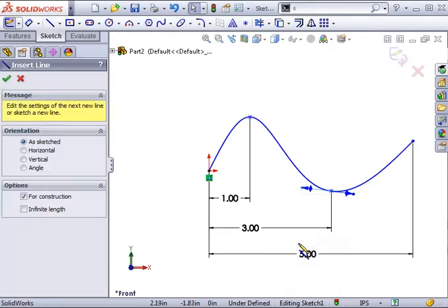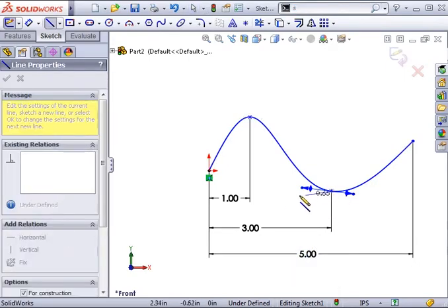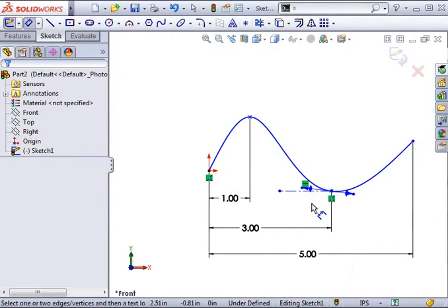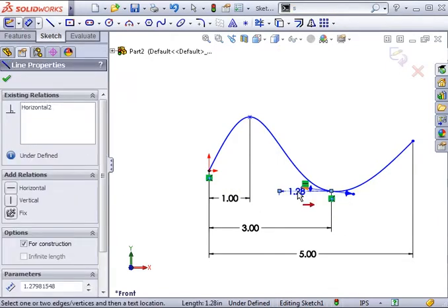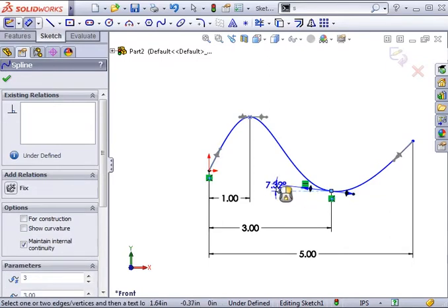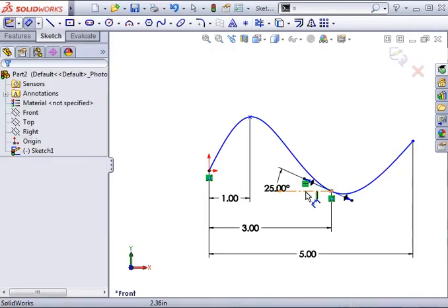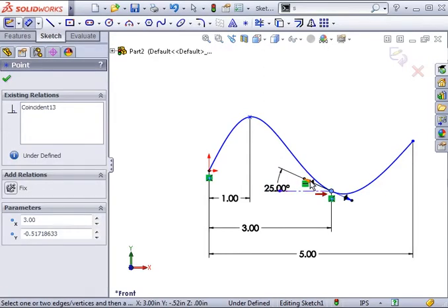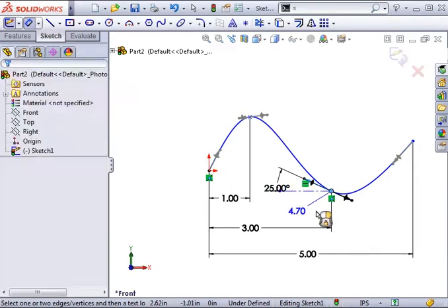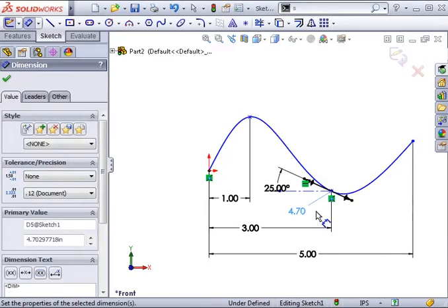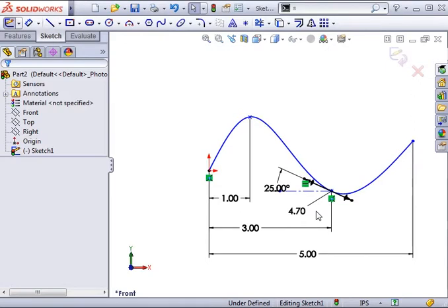Be careful when doing this, because if you exaggerate the angle or magnitude too much, you'll get an error and the geometry will fail. In order to fully define a spline, you must define both the locations of the spline points and the magnitude and dimension of the drag handles. So keep that in mind when using splines to create geometry. The more spline points you add, the more work you'll have to do to fully define it.